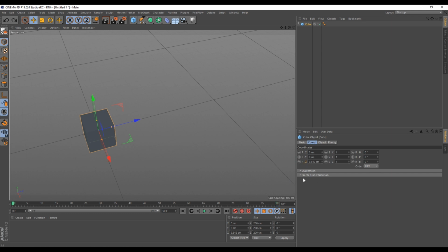The other way we can add a keyframe is by recording our active objects here. And what this does is that it records the entire position, scale, and rotation of your object. So if you don't want to always manually come here to click the position, you can just record it here. So if I check this here, you see that everything is recorded at that particular frame in our timeline.